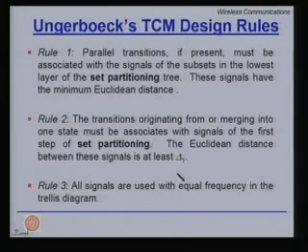These are ad hoc rules, but they work well because there is no way we can know the best way to assign optimally all the symbols to all the branches in the trellis. So, it talks about the diverging branches, the remerging branches, and the parallel paths, and tries to maximize the Euclidean distance based on only these three.